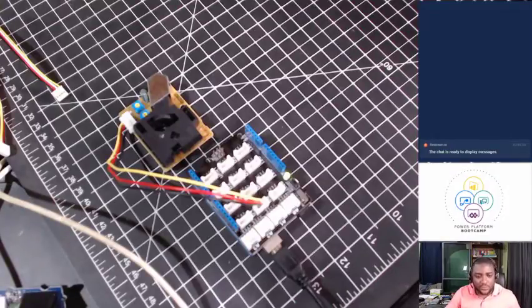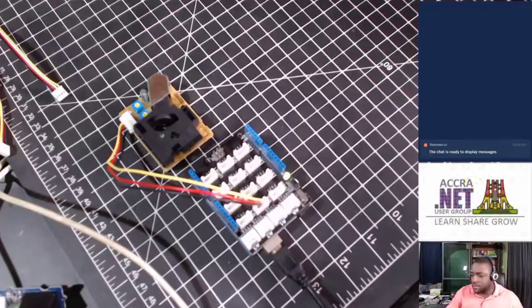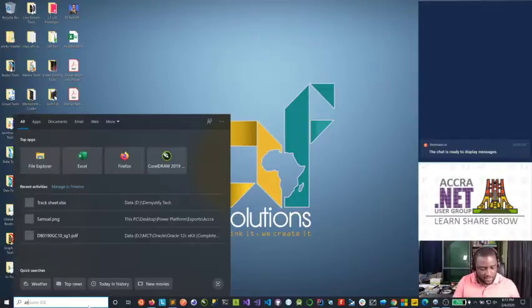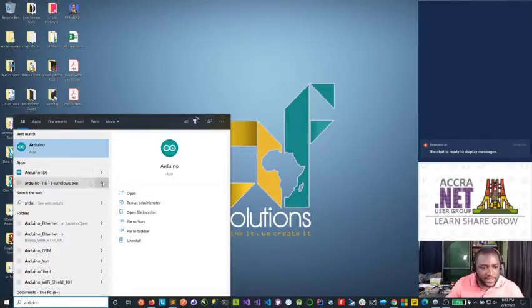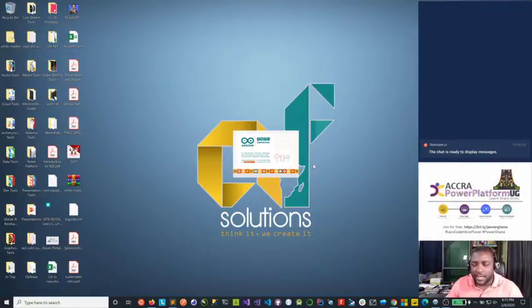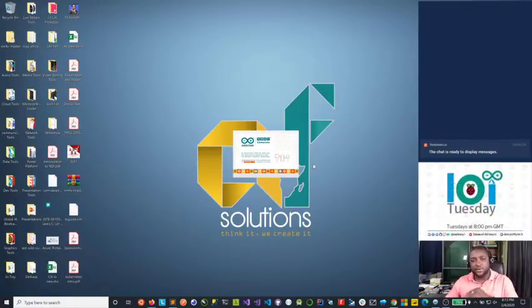Okay, so let me switch back here. Let's go and open our Arduino IDE, not the Arduino app. And like I showed you the last time, anytime you're starting up your Arduino app, ensure that you're using the right COM port for the Arduino, all right?